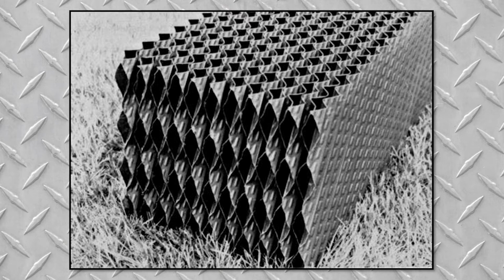Fill can be made out of many different materials, but aluminum is the most common. They're also intended to slow the flow down as it travels from the top to the bottom of the cooling tower, which allows for increased heat transfer. An important thing to remember is that the condenser temperature is key. The whole purpose of the cooling tower, whether it's wet or dry, is to lower the condenser temperature.